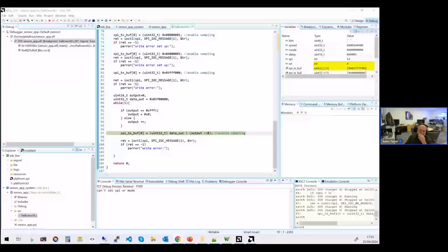So yeah, somebody was asking actually if it's possible to work with FreeRTOS on the Zynq 7000 that uses two processors. Yeah, you can put FreeRTOS on one processor and run it, or you can put it on both processors depending on how you configure it. You can even have them running in what's called OpenAMP, where you have Linux running on one core and FreeRTOS running on the other.